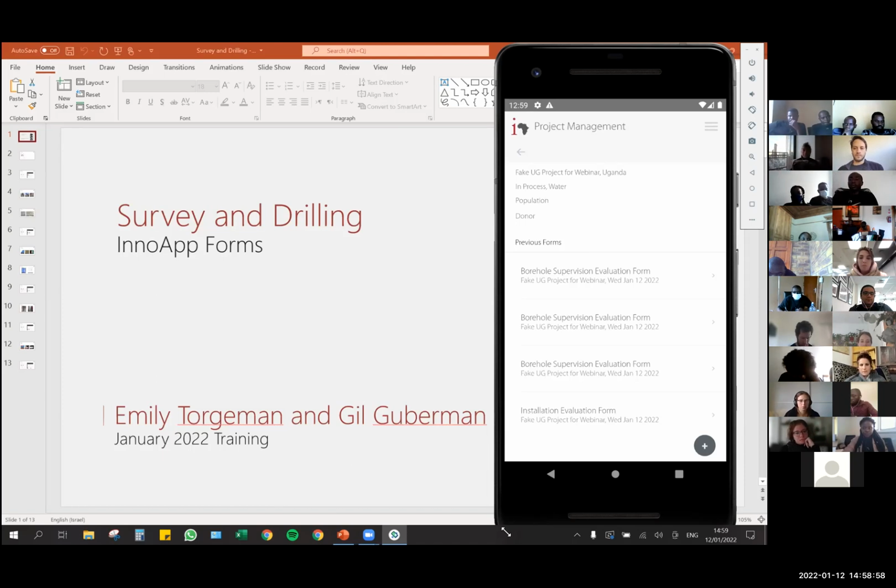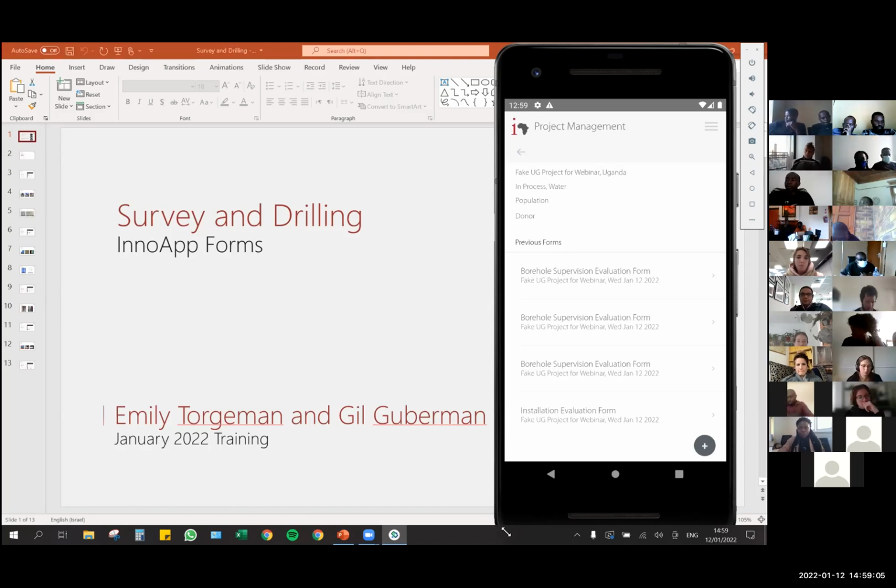We want to make sure, especially with what they call a VES, a vertical electrical sounding, that they're doing it at least 6 points, because we're finding out that sometimes a surveyor goes and does 3 and then says, okay, it's time for coffee, we have to go. So we want to make sure that everybody is doing a full survey and getting as much information as possible.